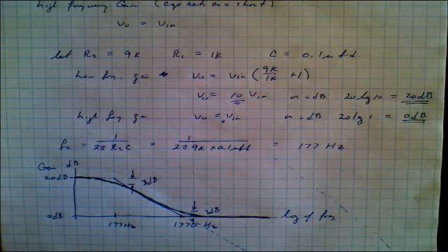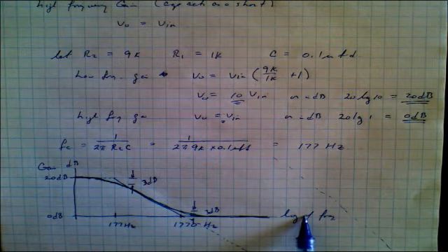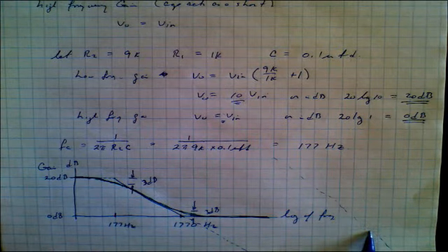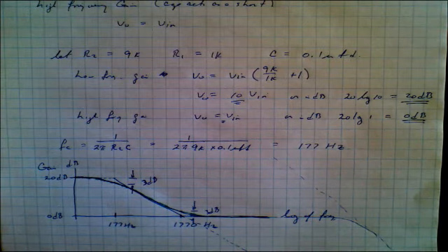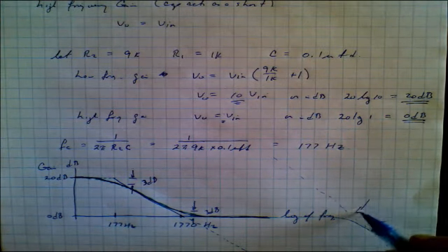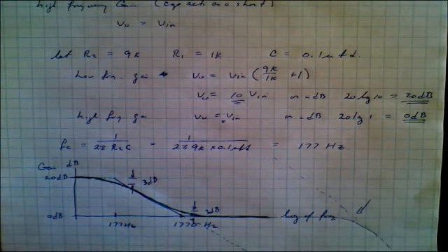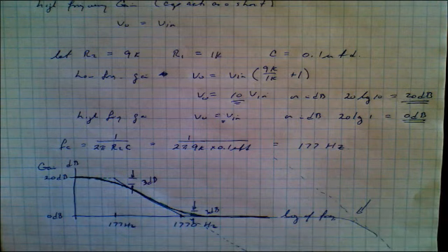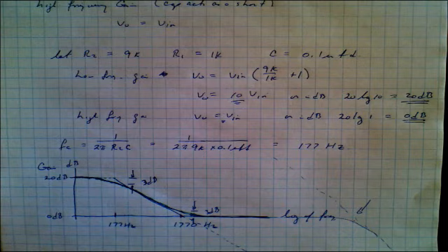And so eventually what happens is that as frequencies increase, it will hit the roll-off of the amplifier itself, way out here someplace. And this, of course, would be defined by the way the amplifier is designed itself. Its own 0 dB gain frequency.